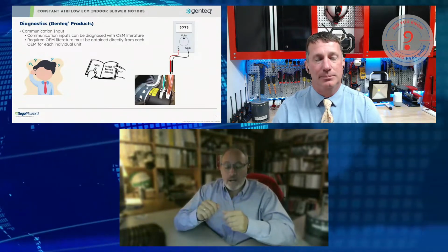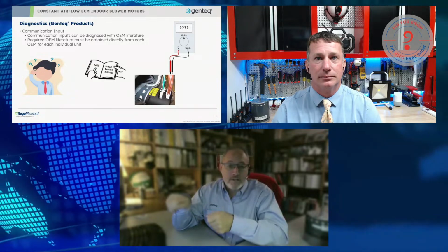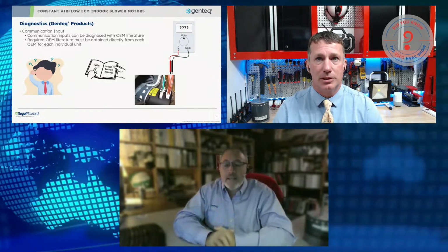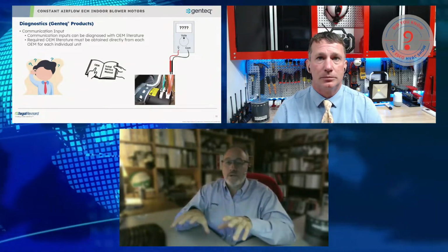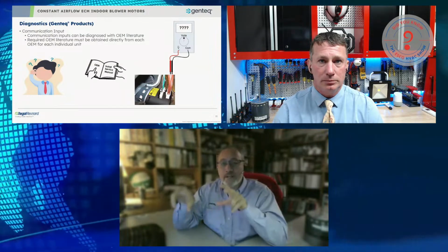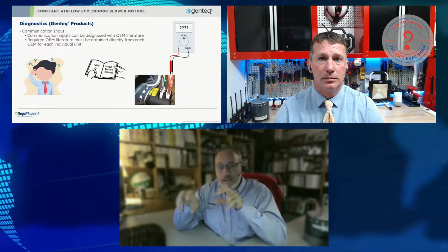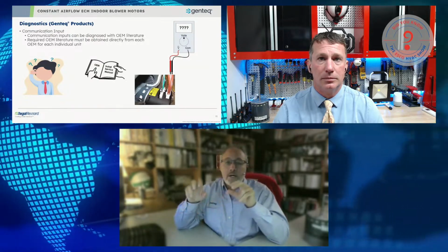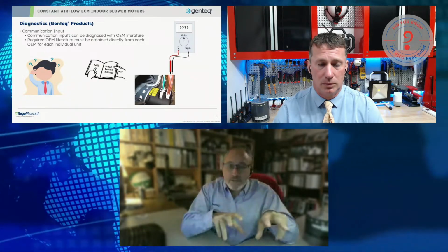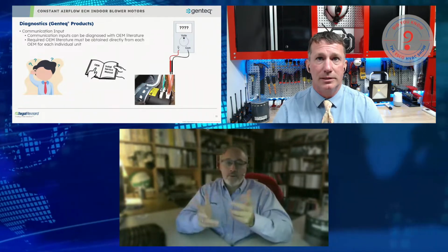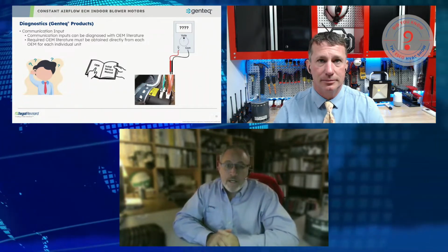Yeah. And then Trane had actually a test kit where you would connect it to 24 volts R and C at the thermostat terminals and plug that in. Now, those processes worked on our motors in their systems, but you couldn't take that process or that connection and do it on our motor in another manufacturer's system because of that unique programming that we talked about earlier. Right.